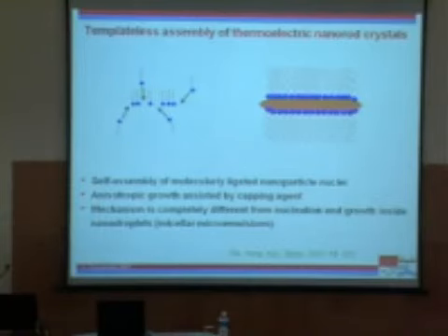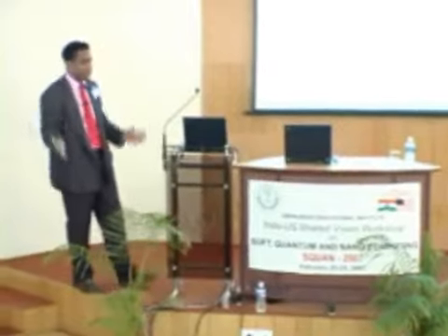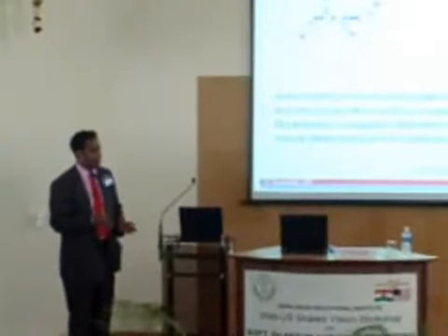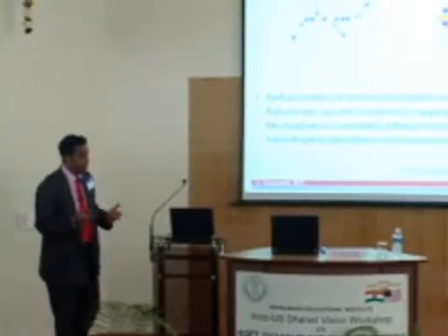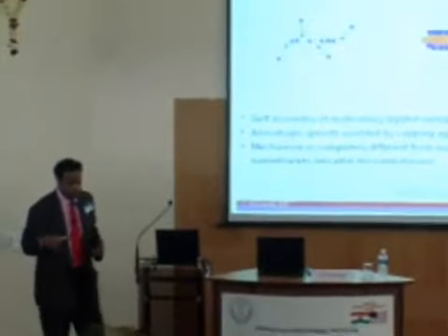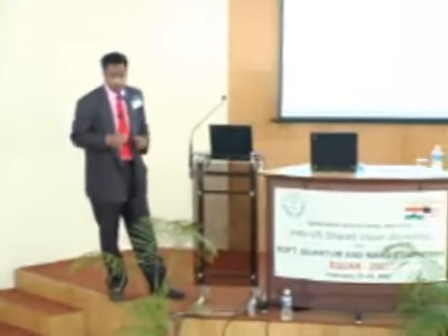Okay, and what I hear from the experts who do this for a living is that even if I were to make a carbon nanotube device right now, and we somehow overcome all the scaling issues and figure out how to separate the different tubes and so forth, most likely it will just blow up, just because of the amount of heat that is dissipated. So we need to really think about ways in which you can get out heat, and this has to be new ways, obviously, because things are happening at the nanoscale, and it's very poorly understood.